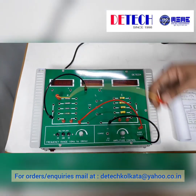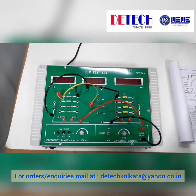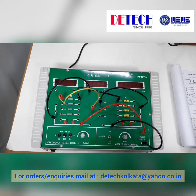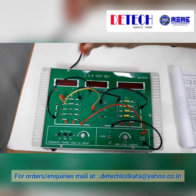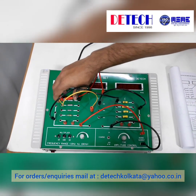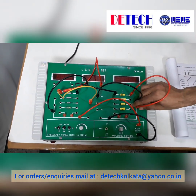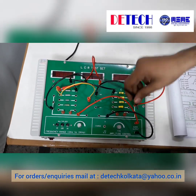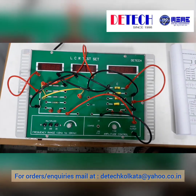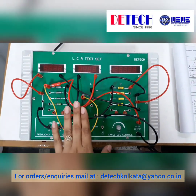We are connecting the series circuit first. So the audio oscillator, the resistance, the milliammeter and the capacitor are being connected in series. After this, the inductance will be connected in parallel. We'll be measuring the input voltage, and the voltmeter has been connected in parallel with the input. This is our final circuit connection. Now we will switch on the circuit and take the measurements, readings.